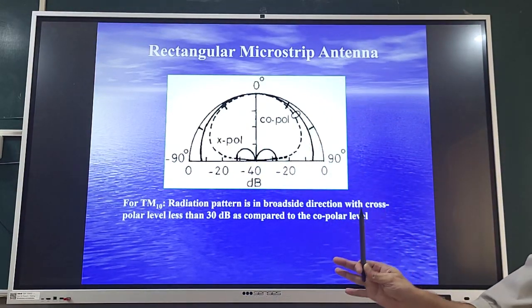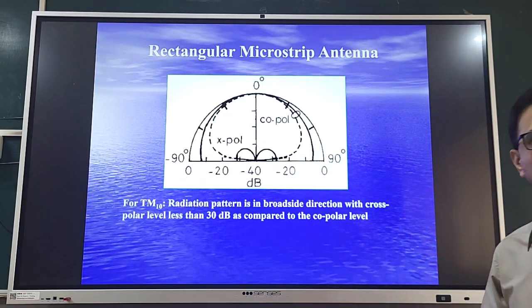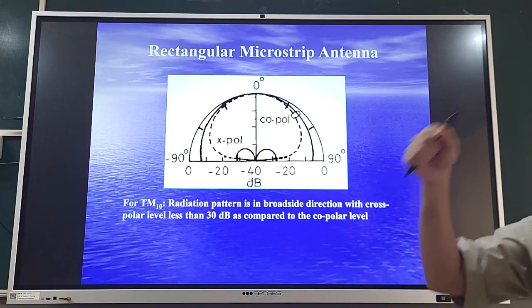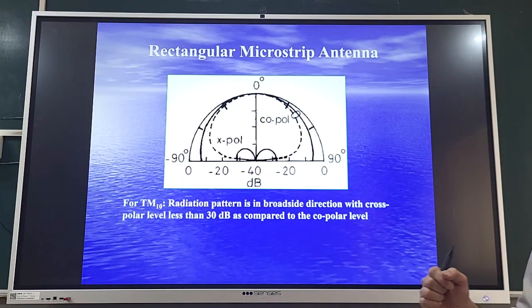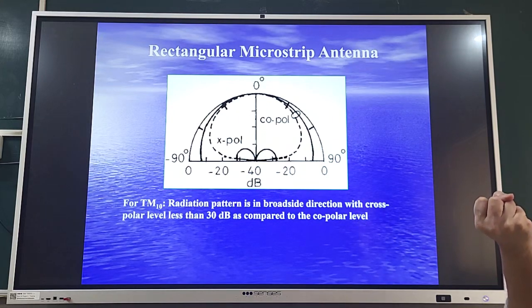Not possible. The received signal polarization is subject to the travel path that the signal undergoes while going from transmitter to receiver. There are multiple reflections. There does not occur a direct line of sight of communication. There cannot be a direct line drawn between the transmitter and the receiver. And in such circumstances, the signal polarization is bound to change. So because of that, my antenna in practical considerations should be able to receive a signal which is orthogonal to its polarization.